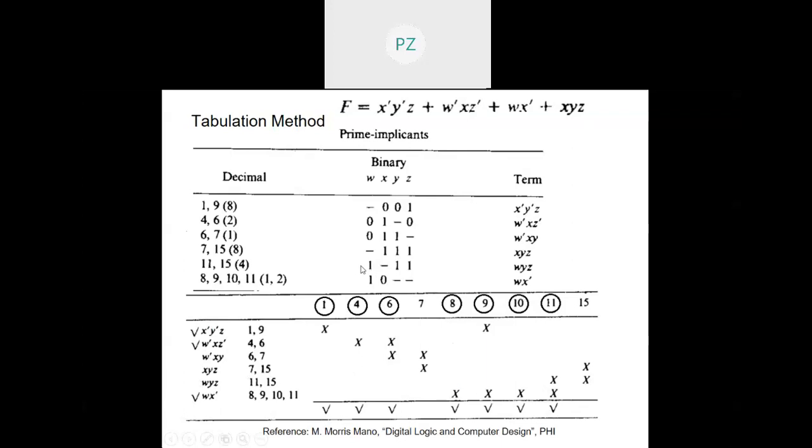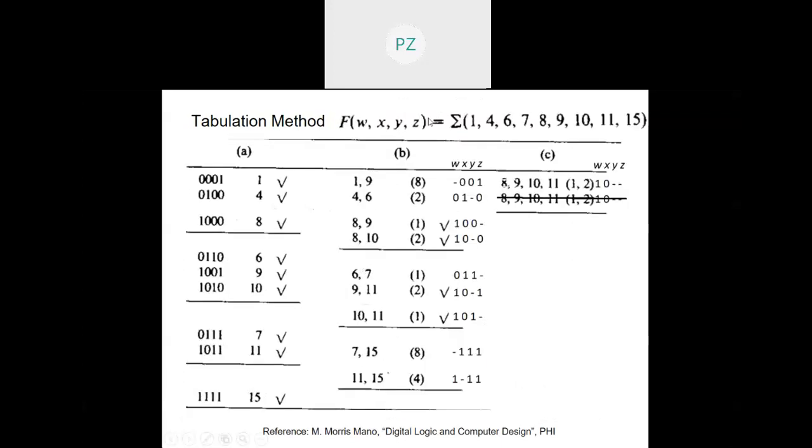So you can repeat the same example by taking a pi here and see for yourself whether you are able to do it or not. And you can always verify using the K-map. Do the product of sum simplification using K-map and see whether the result from the tabulation method and K-map has been coming out to be the same or not. That is why I've taken four variables in it, so that you can verify with a K-map. So that is one thing. Tabulation method can be used equally for both sum of product as well as product of sum simplification.